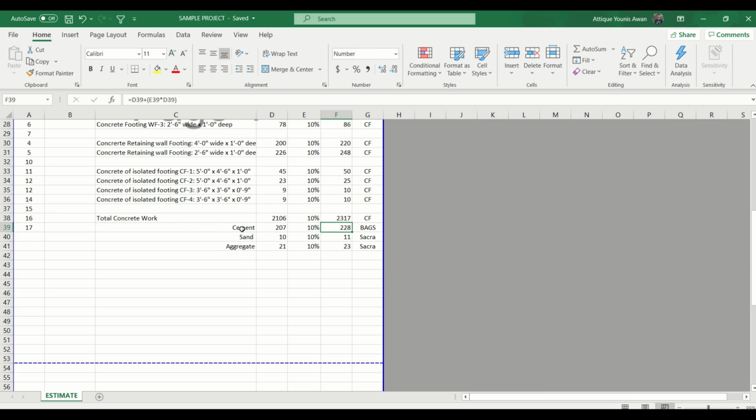So normally for structural members we are going to use 1:2:4. So 1:2:4 ratio we are going to use in our concrete structure works. So what we have to do, we are going to use the same 1.6 for the wet mix, and again we are going to have this much cubic foot, but this time the sum is equal to 7 because 1, 2, 4 gives us 7.